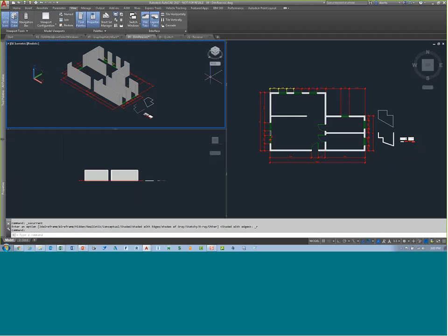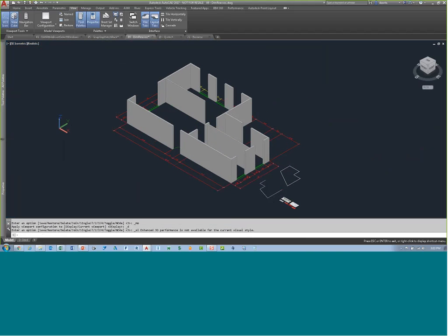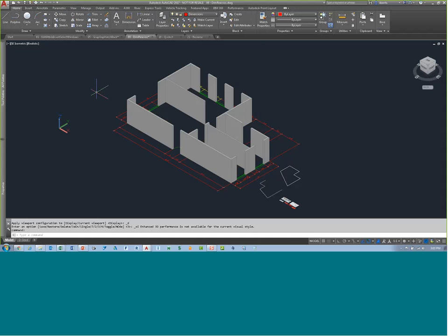Workspaces and profiles. And you know what? Let's switch this back to single for now. When we talk about workspaces and profiles in AutoCAD, these are tools that help you with, number one, the front-end graphical user interface and how things look and appear, and being able to save that design so that you can use it anywhere you want on any other workstation, but also so that if something goes wrong with your graphical user interface, you can reset it. That's workspaces. Profiles does the same thing, but it goes deeper. It works on the back end of the software as well, things that you don't visibly see.